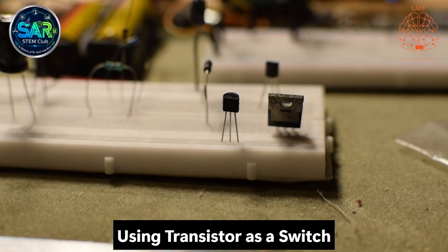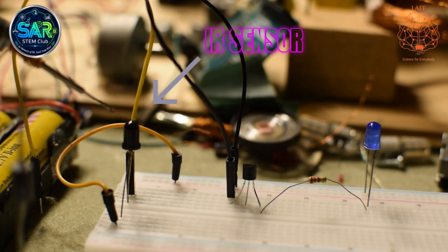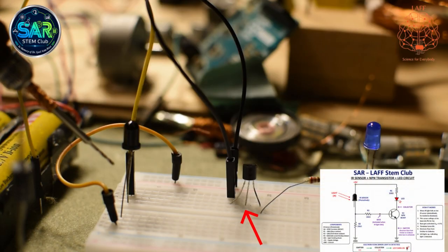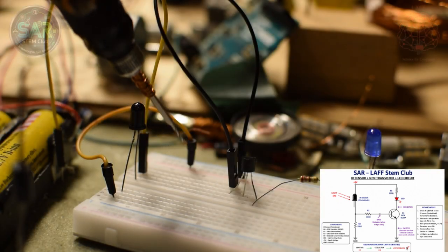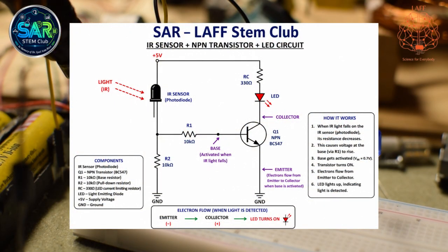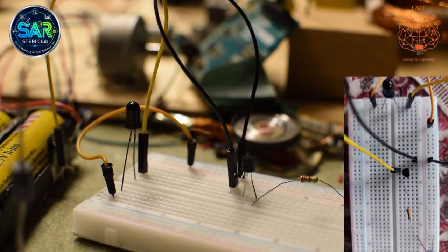Suppose we are building a robot that can detect fire. We connect an infrared sensor, also called an IR sensor, to the base of the transistor. When the sensor detects infrared radiation from a flame, it sends a small electrical signal to the base. This signal turns the transistor on. As a result, current flows through the circuit and an LED lights up. The glowing LED tells us that the sensor has detected fire or infrared radiation. This simple switching action is one of the most common uses of transistors in robotics and automation.